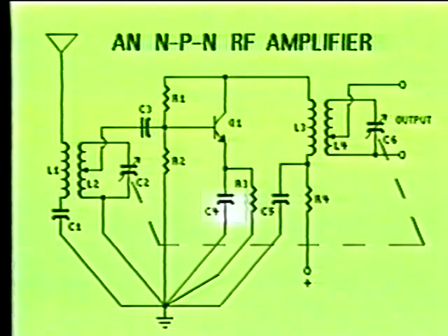Capacitor C4 is used to hold the emitter bias voltage constant even when the input signal voltage applied at the base causes a variation in the collector current, which results in more current flow through emitter resistor R3. Basically, capacitor C4 forms a low impedance path from the emitter to ground, which results in a decrease in the degenerative effect that would otherwise reduce the gain of the stage.